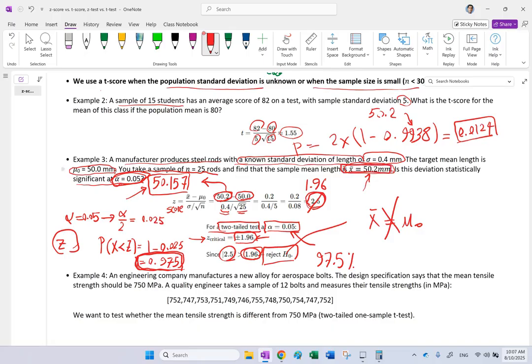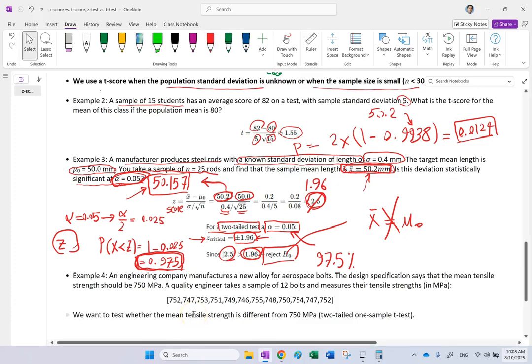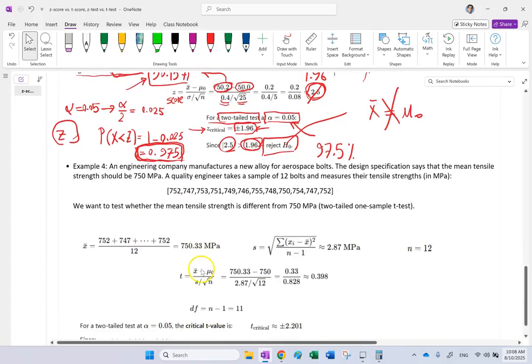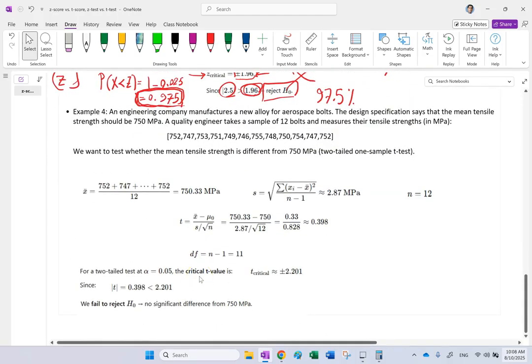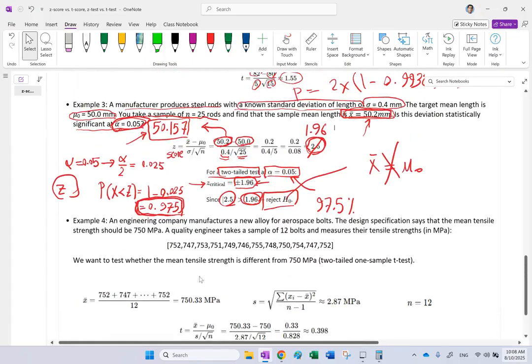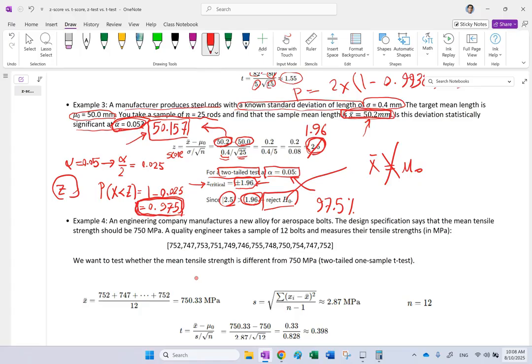These guys are clearly longer than what you are making. The chance of seeing anything this long is only 1%, not even 5%. So these are really rare. And because they are that rare, clearly you are making long rods, and you should go ahead and change your manufacturing parameters so you bring them down below which number? You're right, below this number here.